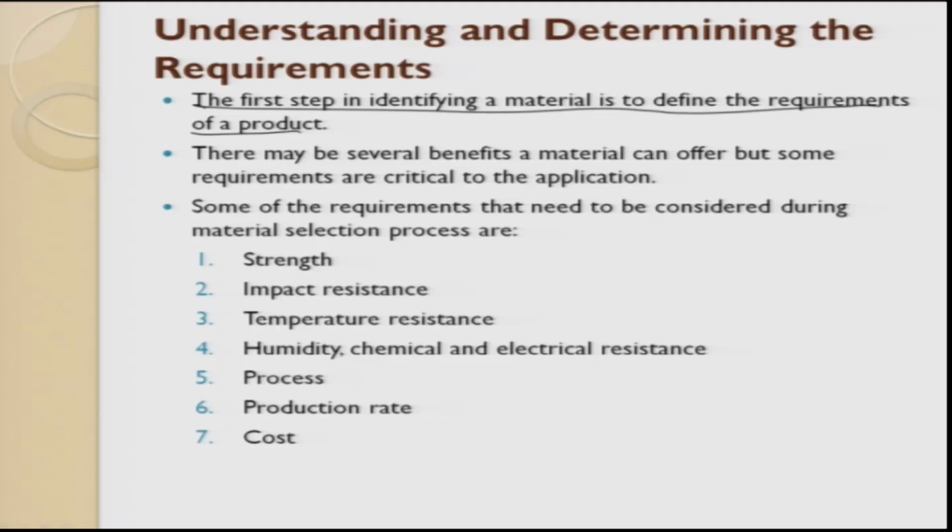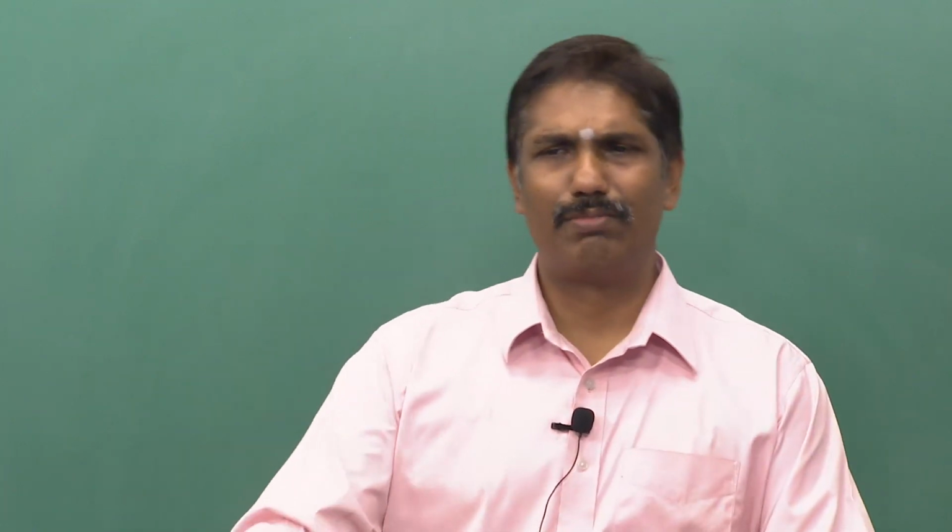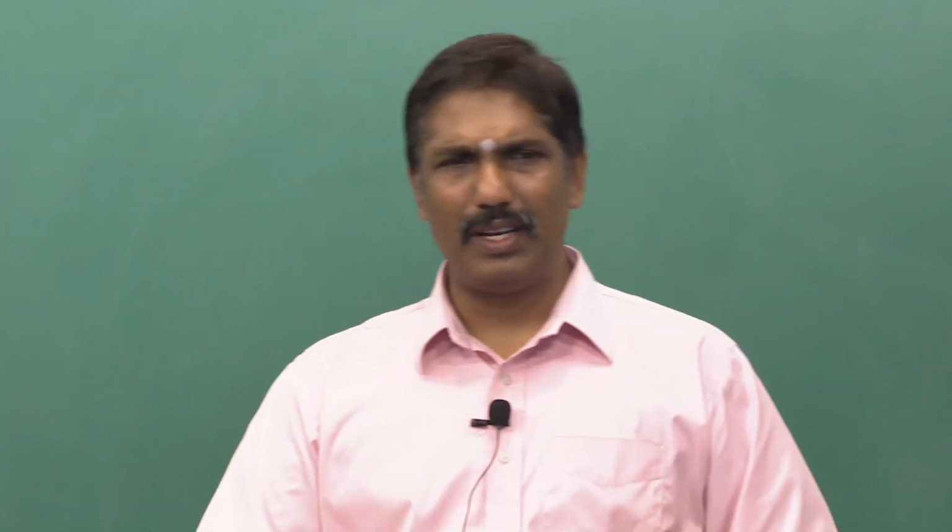The third thing is roughness. It has to be as smooth as possible. The fourth thing is when you sit on a chair, you sit as an impact load. When you sit as an impact load, the chair has to take impact load also. So the toughness should be high. Now you see, we thought initially it is compressive, but now you see a list of properties are required. Mechanical properties are required from a product. And then on top of it, the other things are the color, the texture, all these things play an important role.